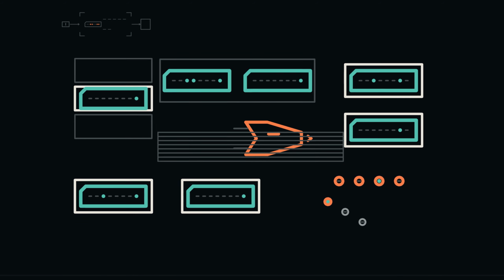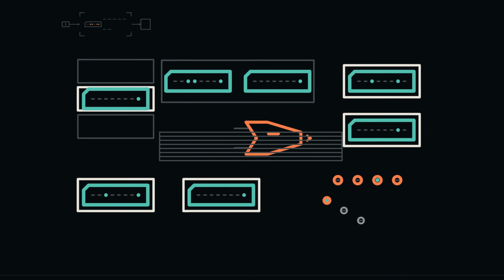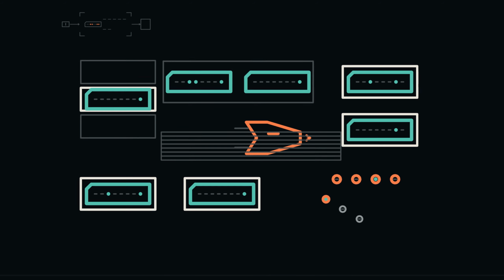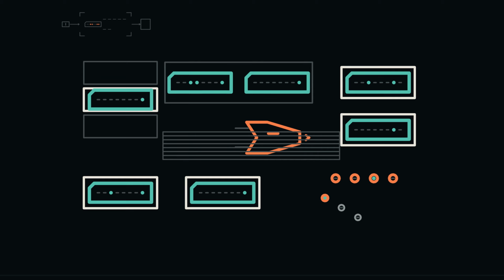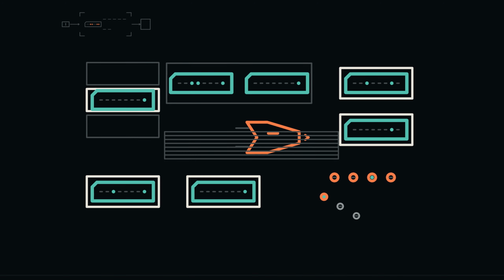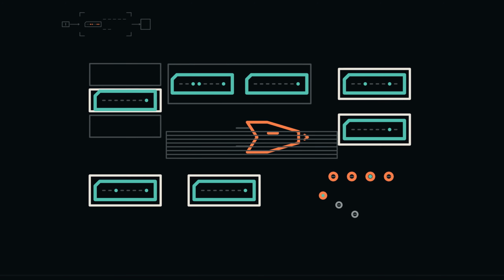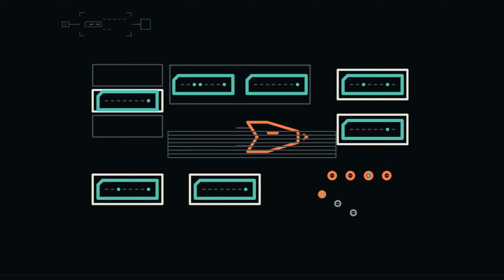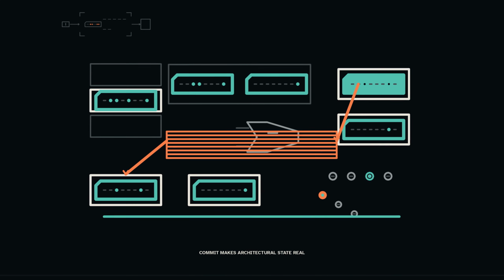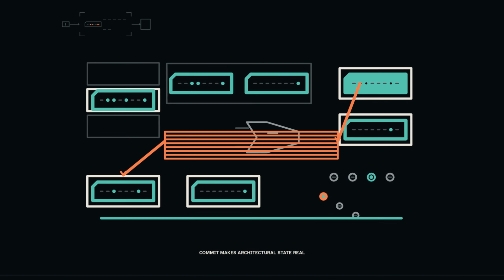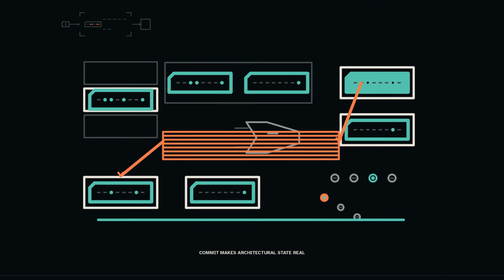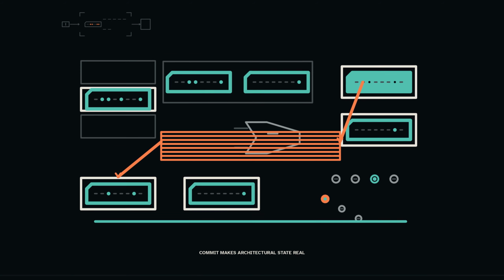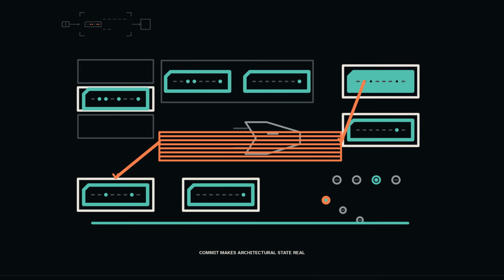The next clock edge will use PC 22 to begin another instruction. Execute is not a vague phase in which the machine does everything. It is one declared state transition built from an already decoded contract. Use the ledger on a fresh instruction boundary. Controller state is fetch 0 address, PC is 22, and the bus is inactive. Name the next 3 committed transfers without seeing them.